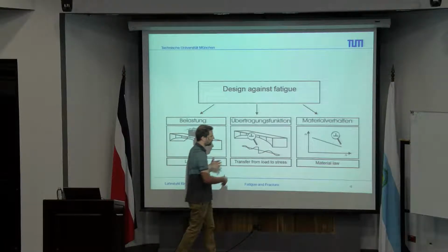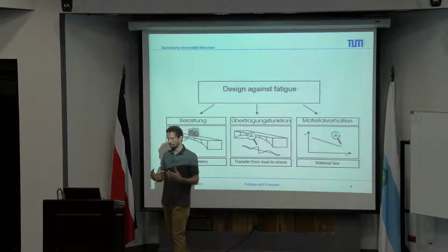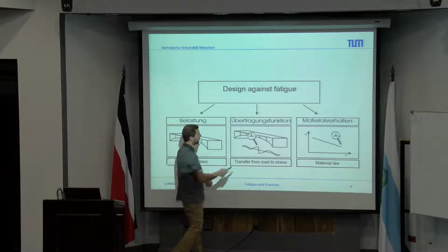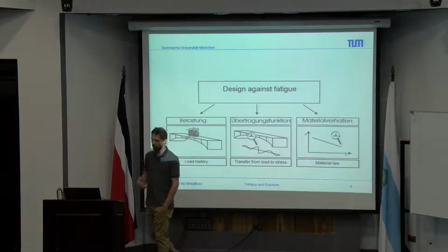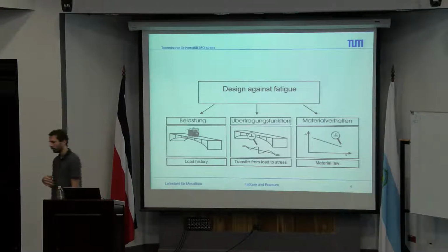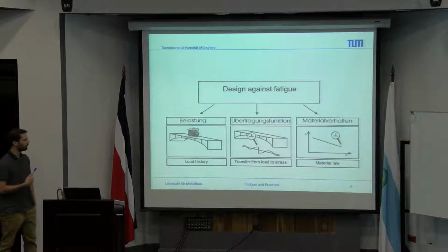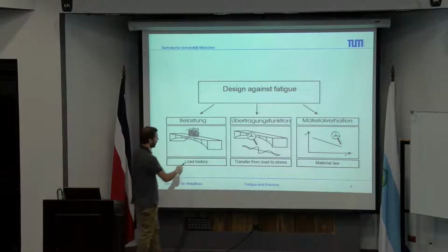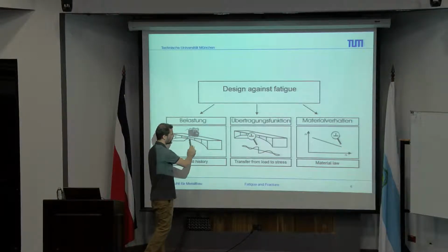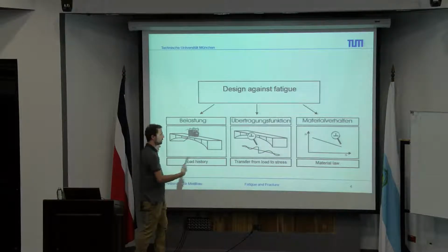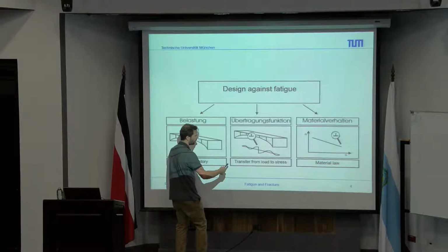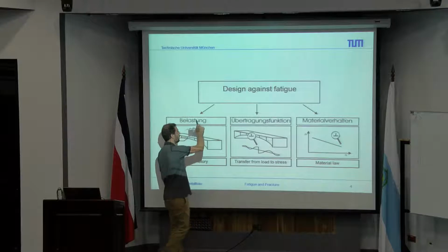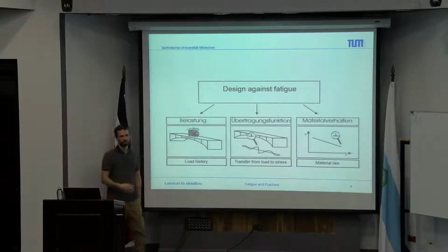At the same time, if you have some further tools, you can use some strain gauges and put them on the most important points to get a really significant stress time signal, and also by having an idea of the loads which are going over your system and some structural analysis, at the end you can also get some information due to the strain gauges about the loads which are crossing your structure.